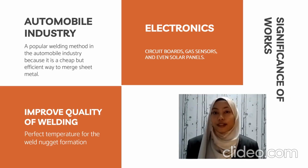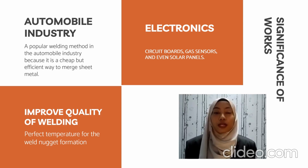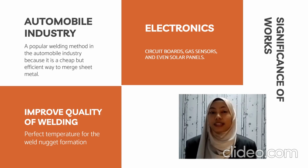Following that, the significance of resistance spot welding is that it is a popular welding technology in the automotive industry because it is a low cost but high efficiency means of joining sheet metal. As a result, it may be used with either trained basic staff or robots because it requires little competence. The bottom line is that the welding process is quick and efficient, resulting in more automobiles produced every shift.